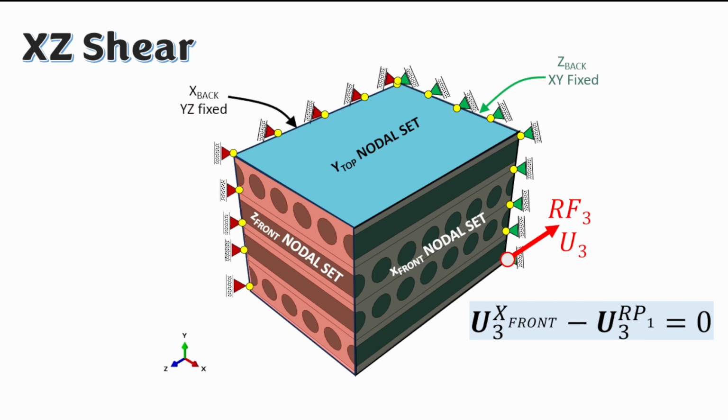Now, the next thing we need to do is to constrain the back end in the YZ plane. And looking at this system, at this point of intersection, you find again that the system is fully constrained in the X, Y, and Z direction, which means that every other thing around here would move in the Z direction and everything around here move in the X direction.